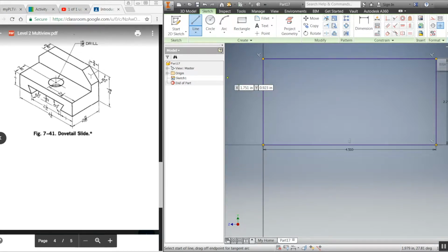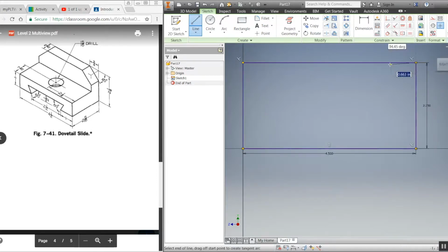Both these corners are the same, and it's 3/4 inch in, and I know it's 45 degrees. So I can just use that to go 0.75 over, and I'm going to go 0.75 down because I know both sides on a 45-degree triangle are exactly the same. So I've got one of that over there. I'm going to do the same thing on this side. And I have both my angles set up for the top two corners.